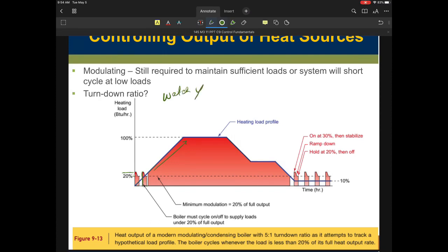And then when the load gets really low, we're sitting there at a cycling rate. The thing I would point out is, when you are doing any type of design, watch your loads. Watch the size of the loads, the loads of the zones. So if you've got a zone that's only 3,000 to 4,000 BTUs per hour, and that's the only zone calling, and the boiler has to kick in, your boiler is producing 20K, but you are only needing